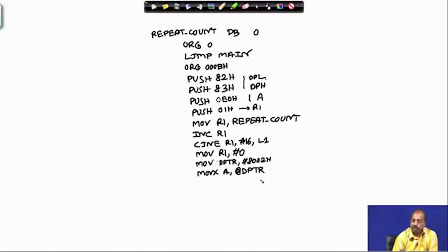That means I have got the second value into the A register. Now I increment A, because 1 second has passed. Next I need to check whether the A value has become 60 or not. If it is 60, that means I have to update the minute part.